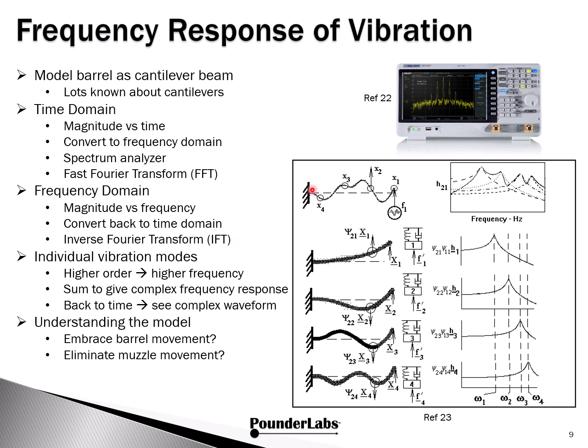So let's look at the motions, the modes of vibration we can see in our barrel. 1, 2, 3, 4 is how these modes are described. This is what the barrel looks like in the time domain, if you could see it. This is what it looks like in the frequency domain. This is the lowest frequency, and you see the spike here, and you'll notice as the modes go higher, the frequency goes higher, and the signal gets smaller.